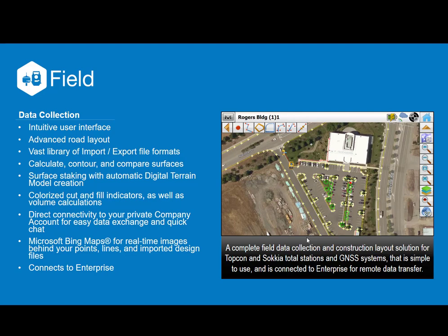There are tons of import-export file formats, so if we're dealing with data from other sources, we can import those. We have the ability to do calculations in the field, do contouring from the survey data as we're collecting it, and do surface comparisons to get basic volumetrics in the field. We have the ability to do surface staking, colorized cut and fill indicators.